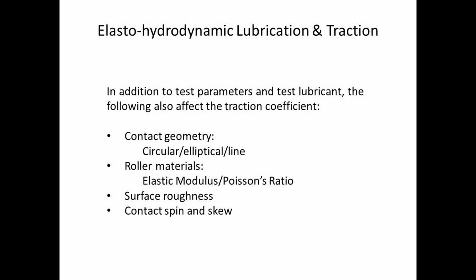In addition to the test parameters and the test lubricant, the following also affects the traction coefficient: the contact geometry, whether circular, elliptical or line, roller materials, the elastic modulus and Poisson's ratio, the surface roughness, and whether we have any contact spin or skew.